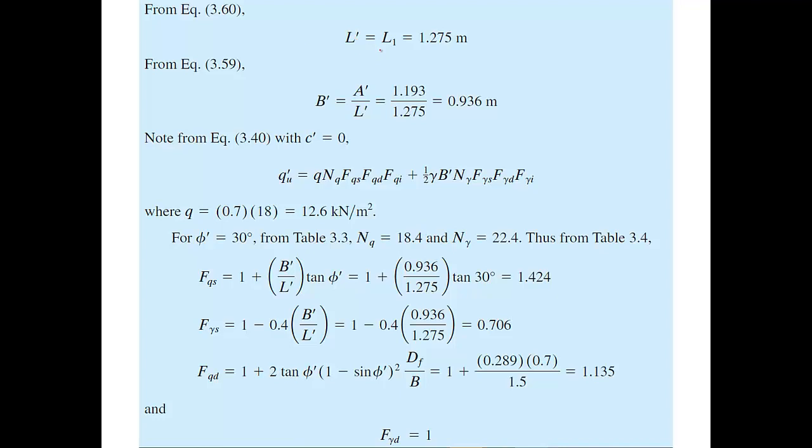And after that, we already selected what is L prime, right? So we know that since we are considering our footing or foundation to be more or less rectangular, square or something like this, very straight away you always consider A prime is B prime into L prime, right?